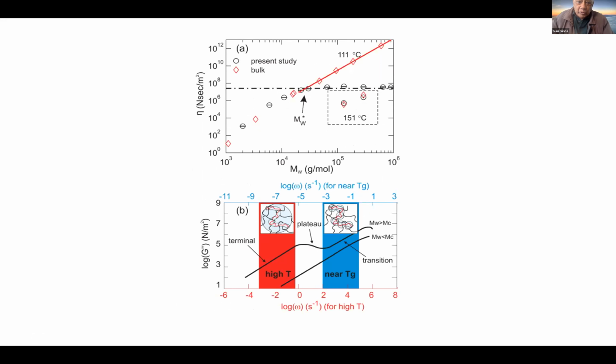When it approaches the glass transition, you get a series of blobs, which are the entangled blobs of polystyrene. And within these blobs you get this diffusion, so after the molecular weight becomes bigger than that, it's as if you were just studying the motion inside these blobs, not in the whole big macro chain at all. And to the polymer physicists, that was obvious.